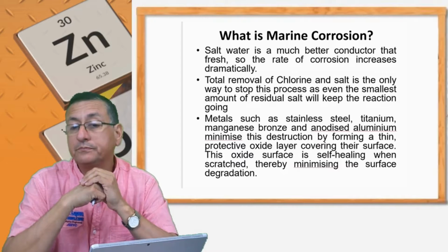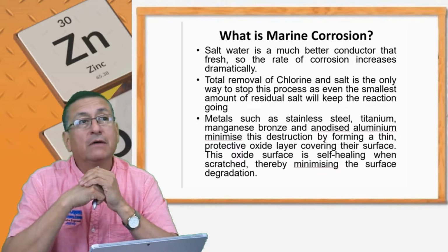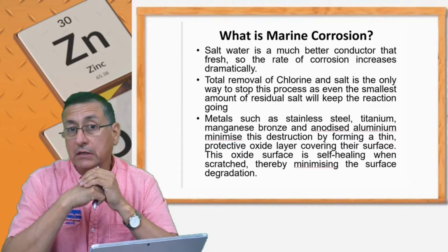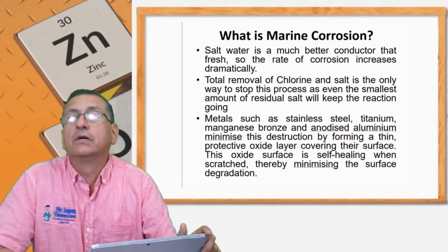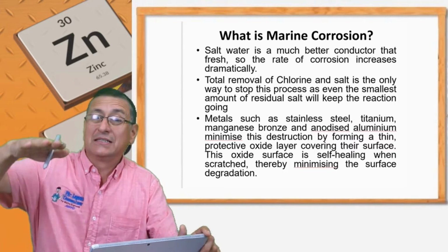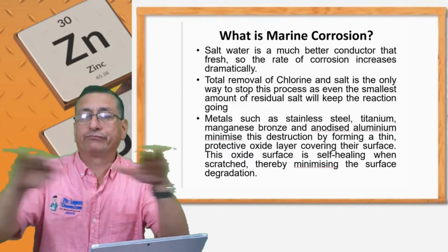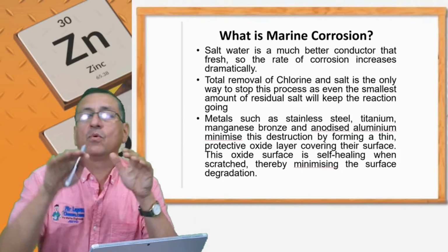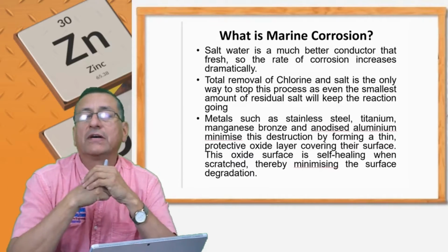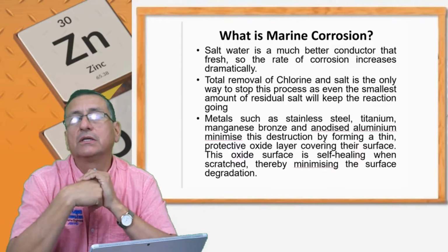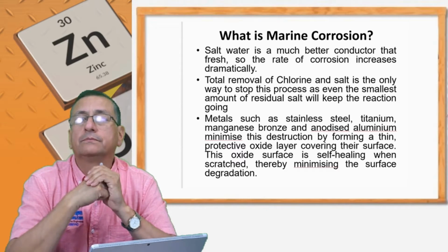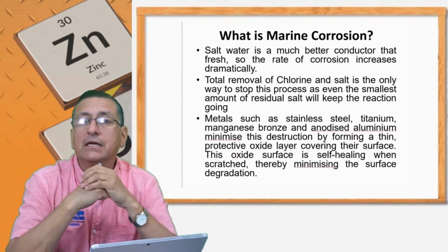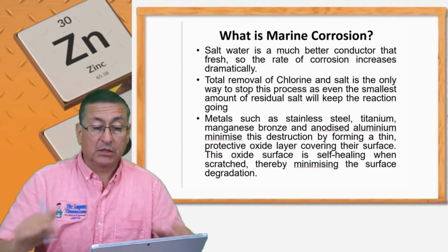For that reason, when you have a problem of a high level of salt water in the bilge of your boat, in the engine room, and the salt water reaches the level of the batteries, finito. If the salt water touches both terminals, the batteries are destroyed. The batteries go into short immediately, short to ground. Yeah, okay. Salt water is a good conductor.